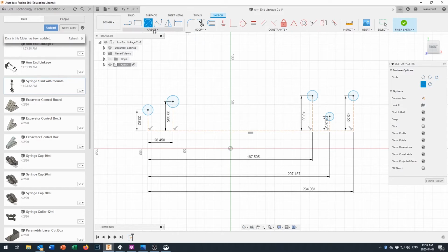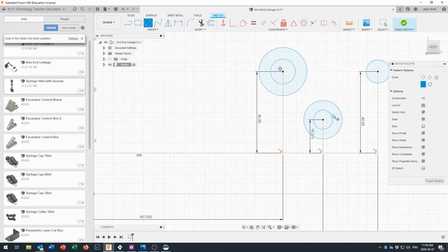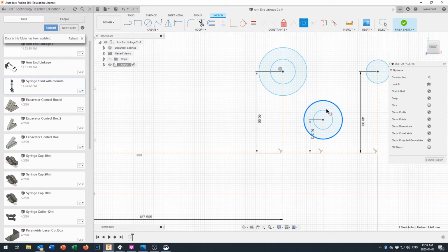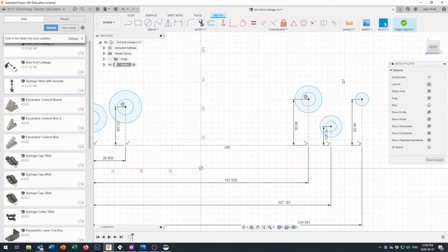And so let's come along here, and now those are going to be holes, so we need a circle that goes around them. And here we do want some constraints, because those will be concentric constraints, so you can see the little concentric symbol pop up after I make it. Which one of those did that not show up as concentric? Let's just make sure that is concentric. If you didn't see the concentric symbol pop up on any of these, hook that up and it says, okay, it's over constrained. That constraint is in there somewhere.